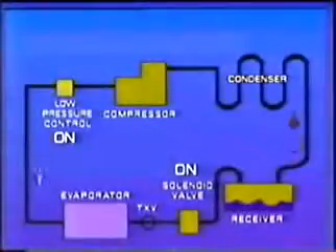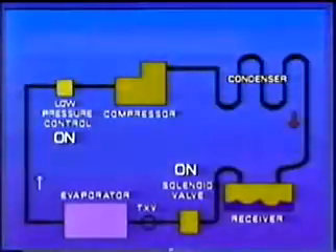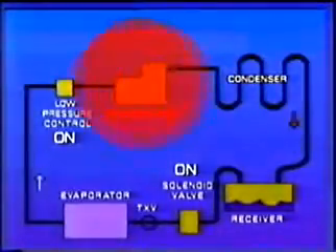Overheating problems occur when the oil in a system is heated to the point where it loses its ability to lubricate. If the heat is high enough, the oil breaks down chemically. Now, the generation of heat is a natural result of compressor operation. Motor heat, friction, and the heat of compression are all considered when designing a compressor. So if the compressor is kept within design limits, no harm results. But extended periods of overheating will bring premature failure not only to the individual compressor, but to the entire refrigeration system as well. Oil and refrigerant break down in severe overheating and create carbon and acids, which can cause harm